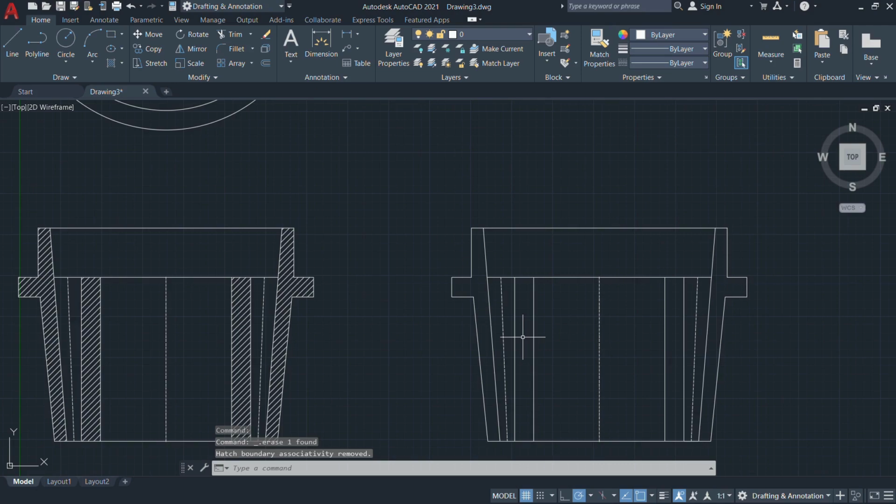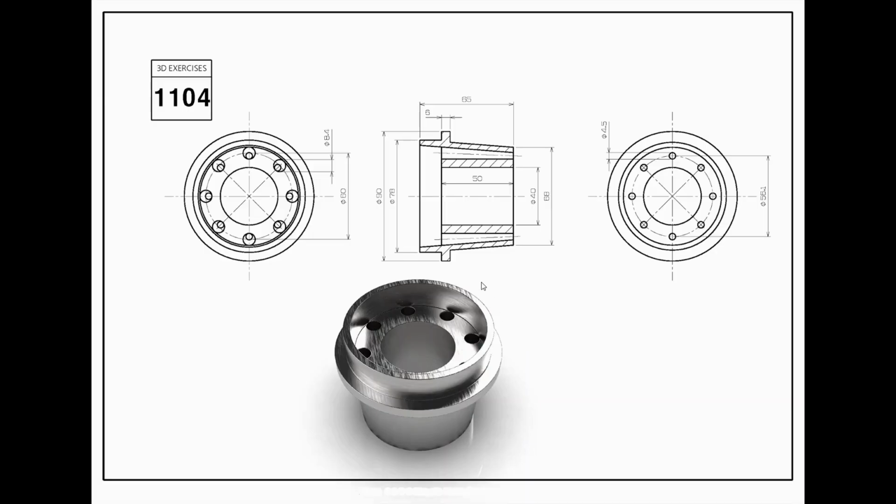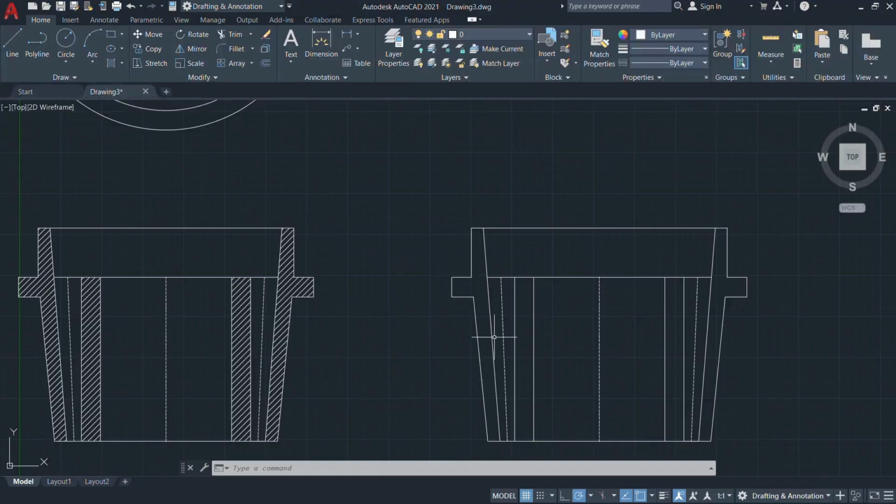First, I delete these hatches and I am going to change the reference line mode into hidden lines, because whatever locations we cannot see from our eye point of view on the left side or right side views, we need to indicate that. Before that, I just use the X command to explode these multiple profiles and join only the initial regions. That is the required region. Type the command J and choose these continuity profiles. Again, type J, select these opposite portions, enter it. Once we join the profiles, select this line and change the mode into hidden lines.